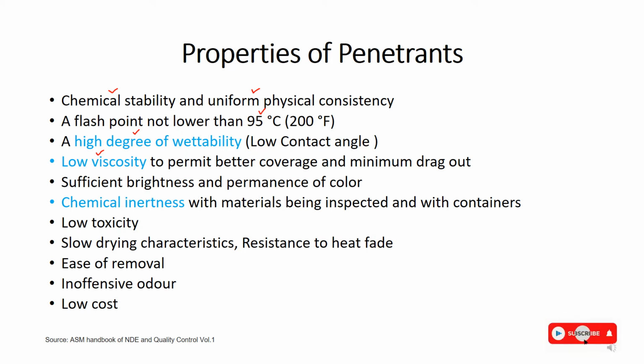And it should have sufficient brightness and permanence of color, so that whether you are seeing it in white light or in UV light, you should be able to see it properly. It should be chemically inert with the materials being inspected and with the containers in which it is stored.